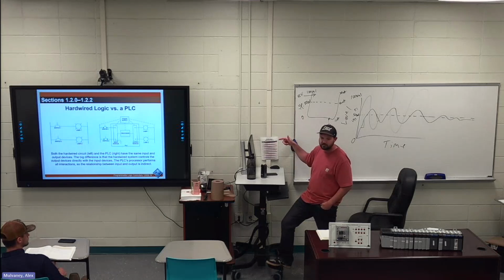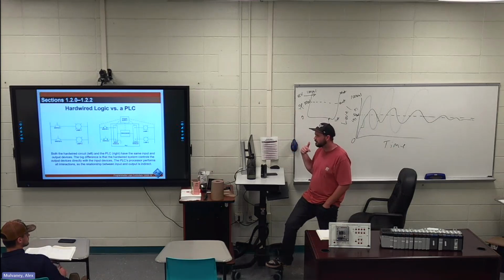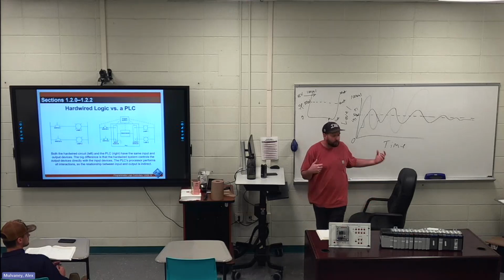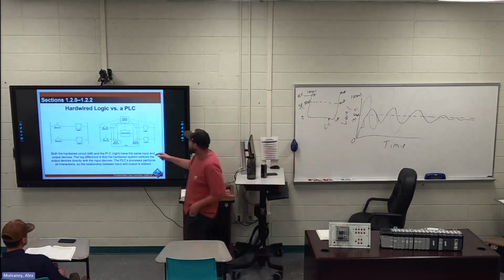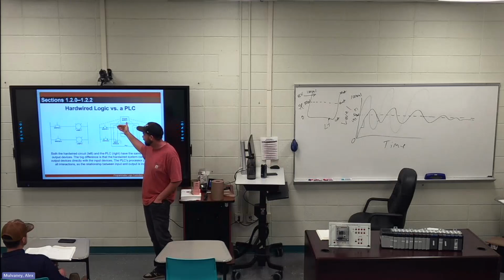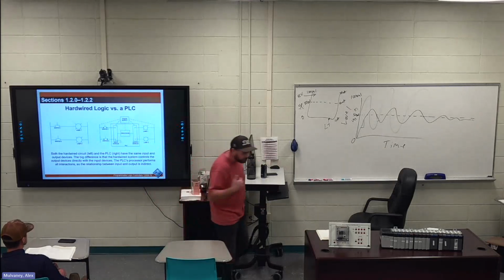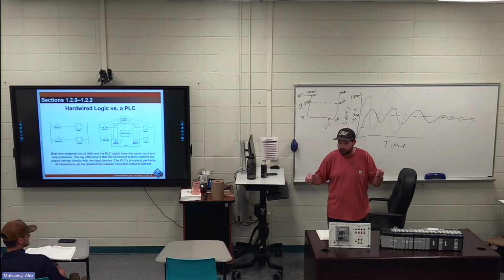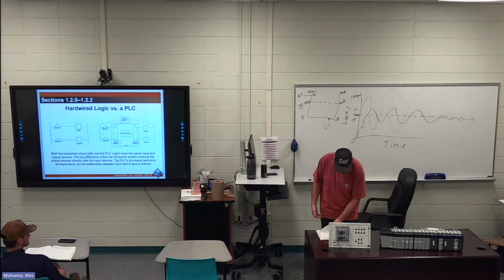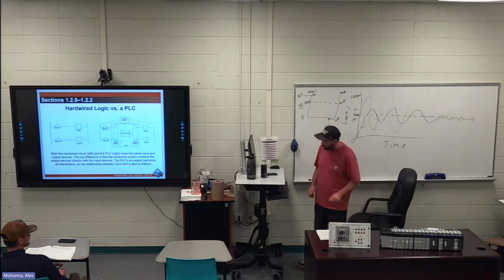Like that input is either missing or something like that. Stuff would show you faults. Like if something like 4 to 20 milliamp wiring got crushed somewhere, it would be very easy to see because scrolling through, this usually would say on or off, and it would just be all question marks or X's. It was a great troubleshooting tool. Rather than, think about a reversing contactor station, you're out there with a meter checking every single coil, seeing if that coil is being called to be turned on. Answer those 5 questions on page 6.